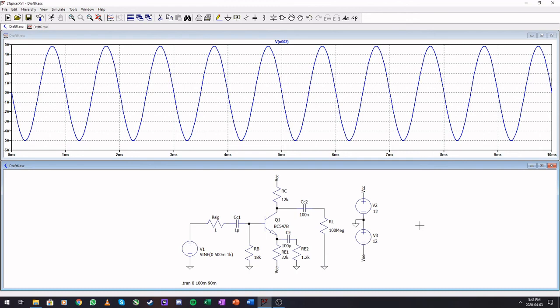I will revisit the FFT when we are looking at an oscillator example in a later video, but this will give you an idea of the non-linear effects of a BJT and what's happening if you drive this input to be much larger than 10 millivolts at VBE. We can drive this one quite high because we have a very large input impedance and a quite nice drop across this emitter resistance here.